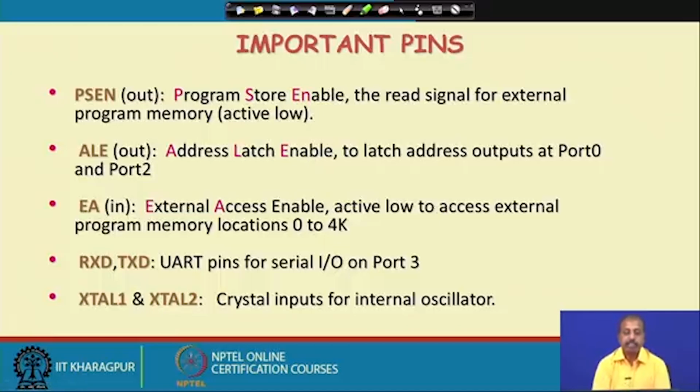Next important pin that we have is the PSEN, or the program store enable. This is the read signal for the external program memory and it is active low. So, we will generally call it PSEN bar, telling that this is an active low signal. This is similar to the